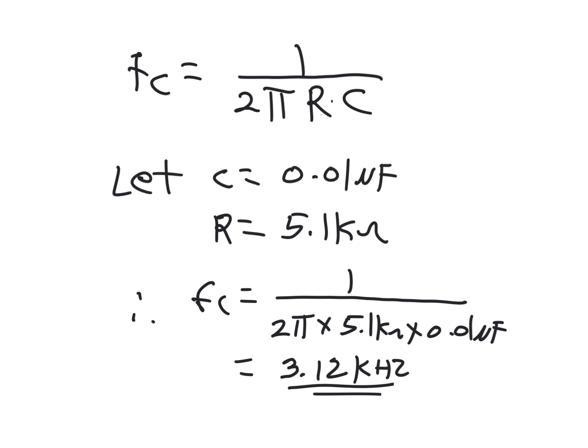So you can see then just by playing with the values of the capacitor and the resistor, then you can set FC to whatever value you need to be. Okay. All right. Hertz. Yeah.